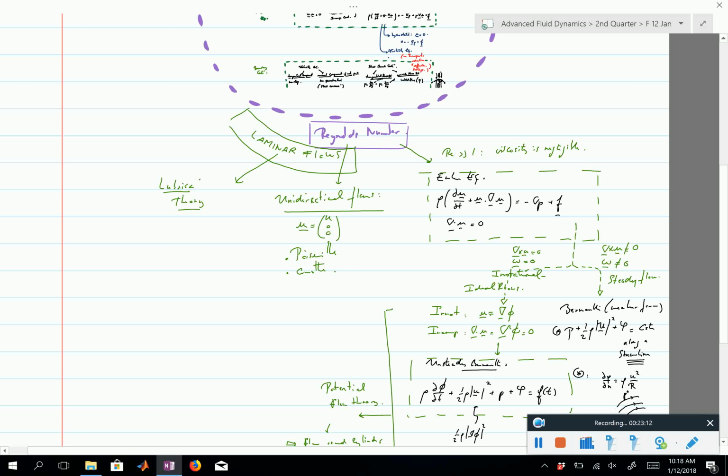Remember, in lubrication theory, it happens when you have a thin film, so different length scales across the flow and in the flow direction. Across the flow, you have a small length scale, and it depends which Reynolds number you pick, but let's say the Reynolds number based on the longer length scale times h squared divided by L squared. When this is much less than 1, then you're in the lubrication limit.